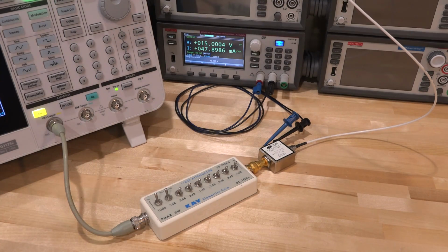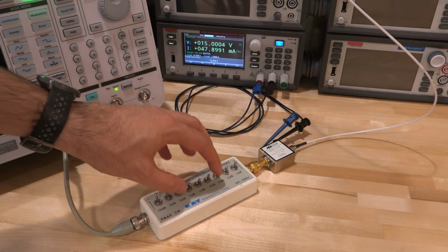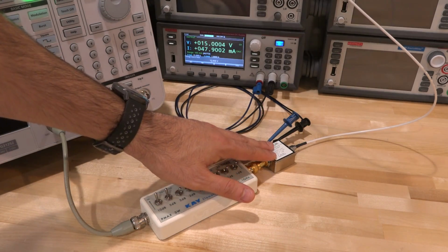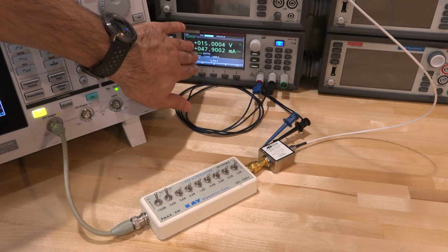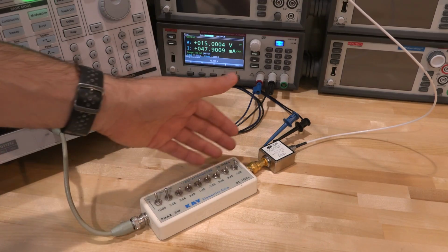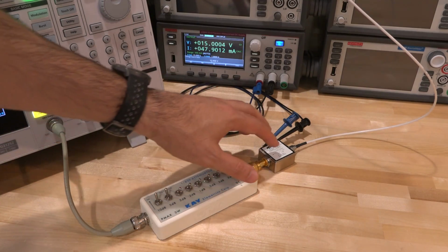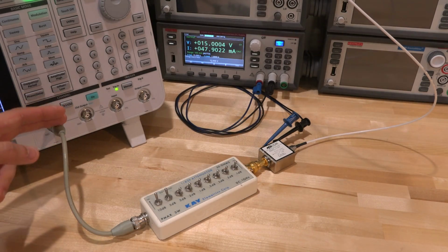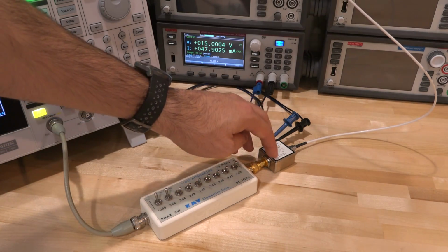And here's our setup for our amplifier. I have a mechanical attenuator here directly connected to the output, and that goes into the input of my amplifier. And the amplifier is powered by the Keithley power supply here at 15 volts. This allows me to change the input attenuation to the amplifier while maintaining a constant output from the unit itself, and that changes the behavior of the amplifier.